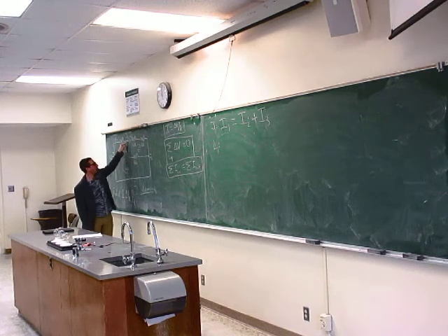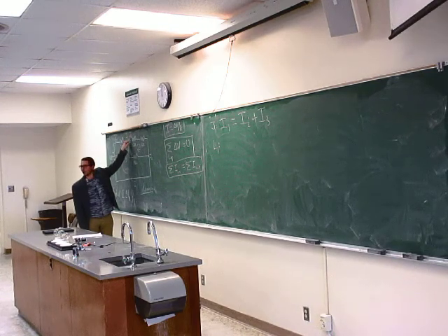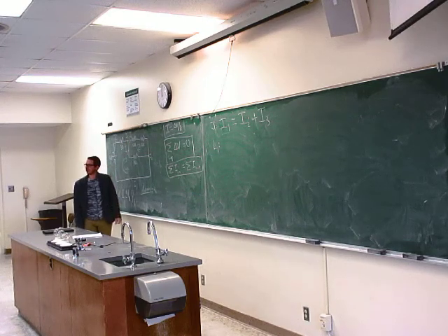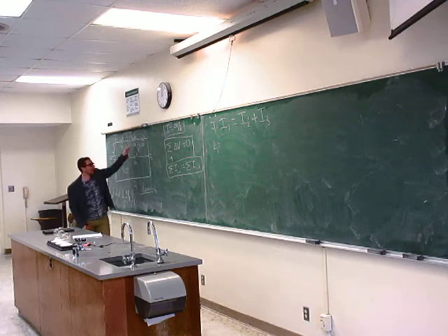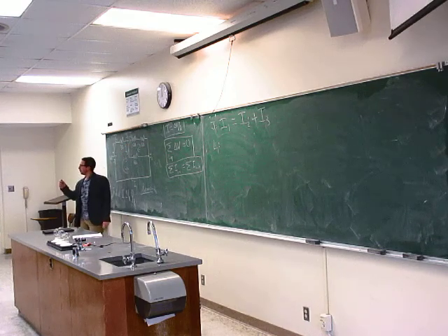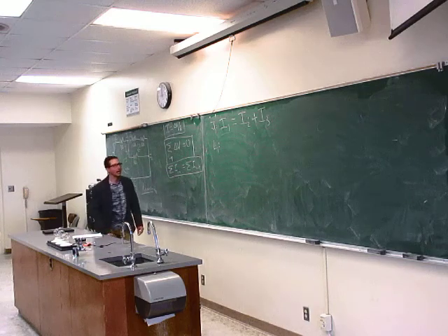So as I cross the 6 ohm resistor in the direction of current I2, what is the change in voltage? Is it positive or negative? It's negative. Whenever you cross a resistor in the direction of the current, you have a potential decrease. Okay, so it's negative.